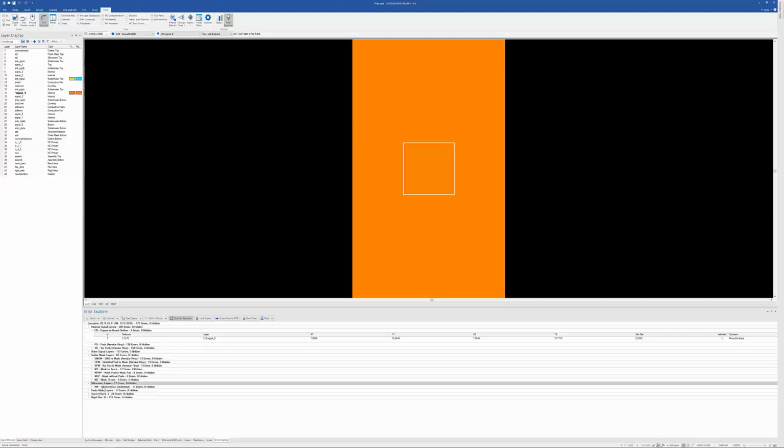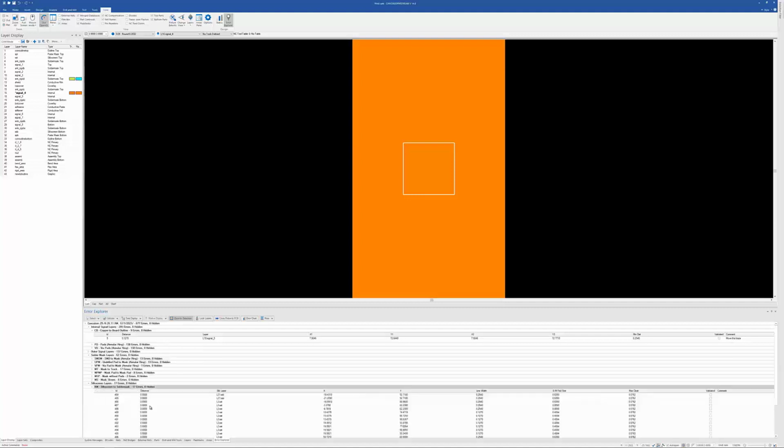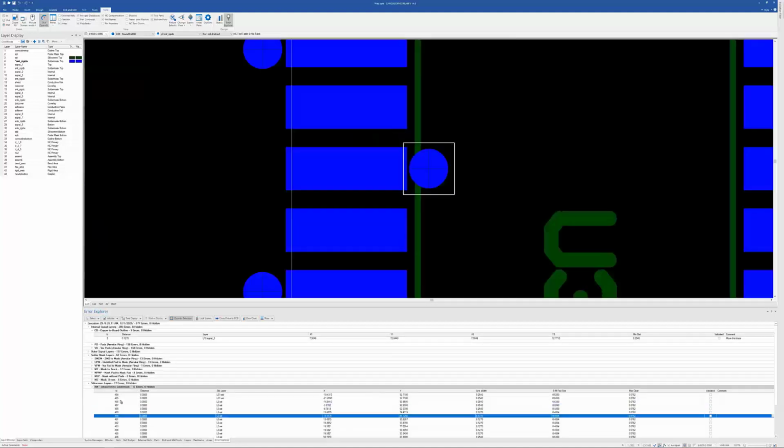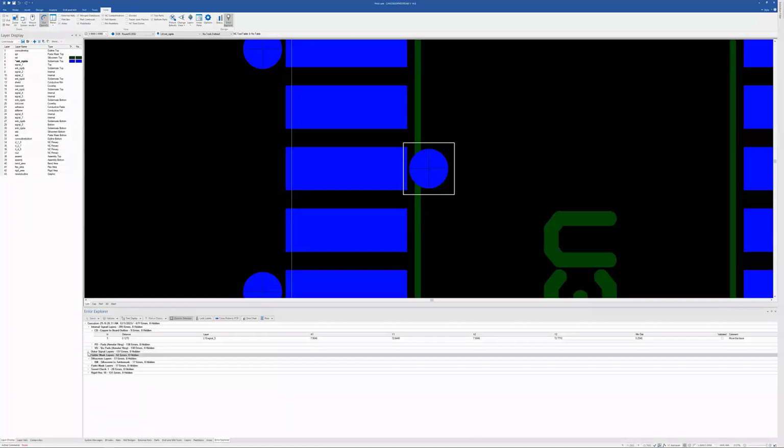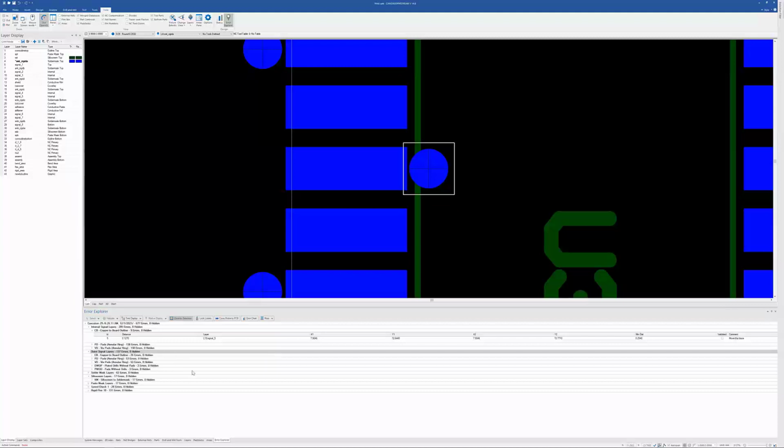Silk screen, yeah, we are putting some silk screen on some solderable areas, and it'll call those out. And then more of your standard copper type checks. Okay, so all told, we can do about 150 different types of checks, and we will report those back to you in the tool.